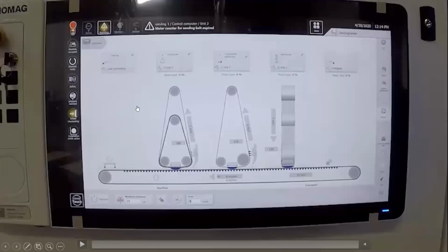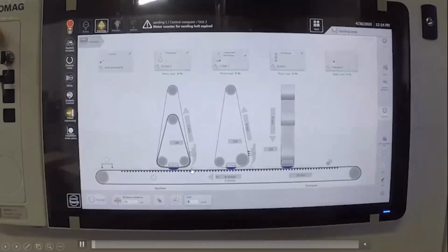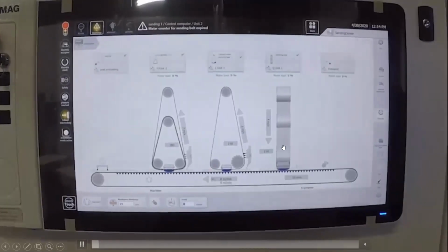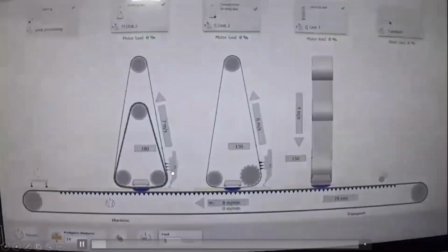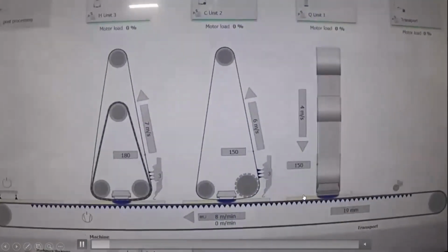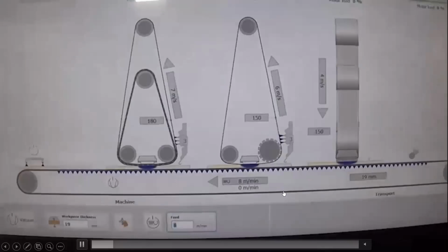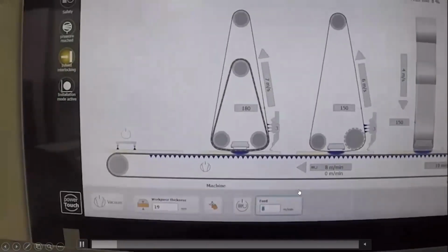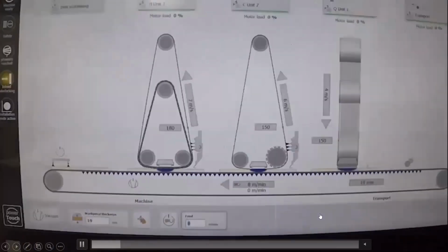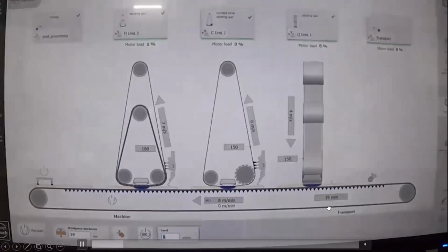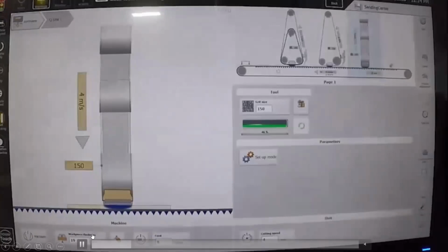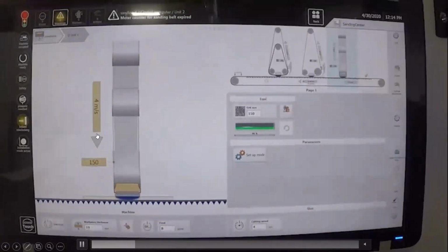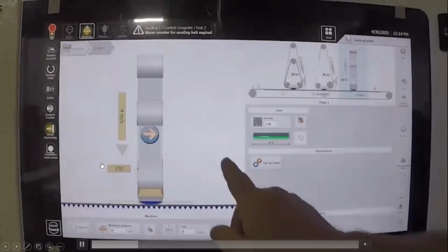So now we're going to look at a machine, a typical veneer sanding machine. Here you can see we have 3 belts: a cross belt, a wide belt, and a chevron belt. All 3 of these heads in the machine that we're looking at here have a magnetic segmented pad inside. Again, we can control feed speed, control thickness, and we have a lot of control with such a head. Every head has a frequency drive, which gives us control over the speed of that head.